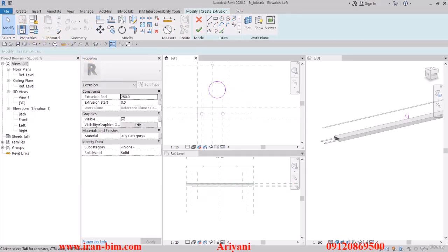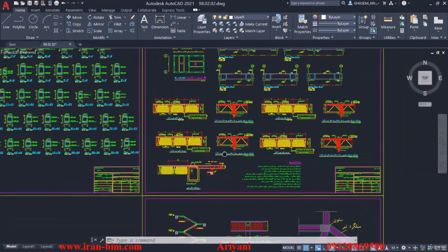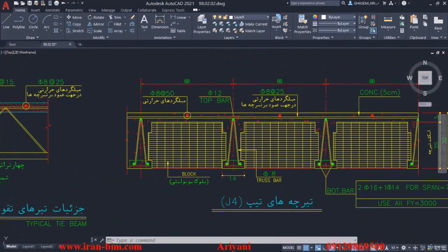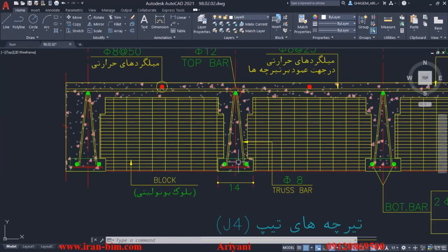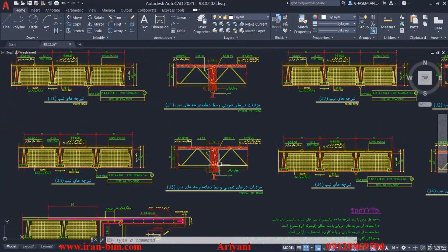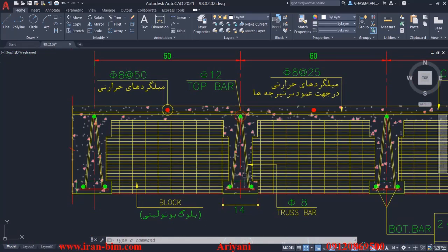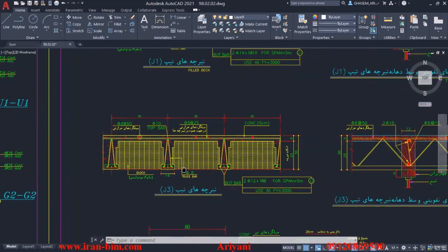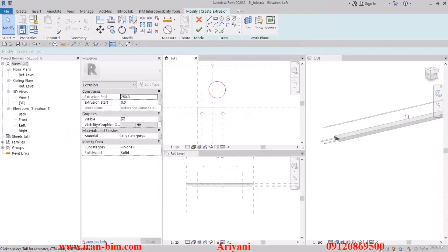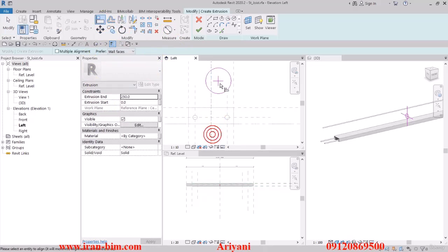And the reason that I'm drawing this one separately is if you take a look at the plan here, we have 3 rebars here and then 2 here. If I were to draw the 4 together like the previous ones, then we wouldn't have been able to turn the visibility on and off for these, because usually we have these 3 now with different dimensions, and the lower and the upper parts have different widths. But sometimes we have the one in the middle and sometimes we don't, like this example here. So make sure you draw this one separately as well.